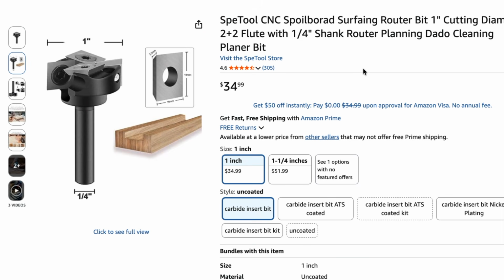This one's going to be the most controversial. They don't really make a Facemill for this machine because the machine doesn't have a lot of power. I can't recommend you hogging material like a Facemill in an industrial environment. If you have access to a machine shop with a grinder, you could get a larger diameter Facemill of like a 1-inch Facemill with a 3/8 shank or 1/2-inch shank, grind the shank down where it'll fit in a 1/4 inch or 8mm collet, depending on your tooling setup. You're still not going to be able to hog material, does not matter.